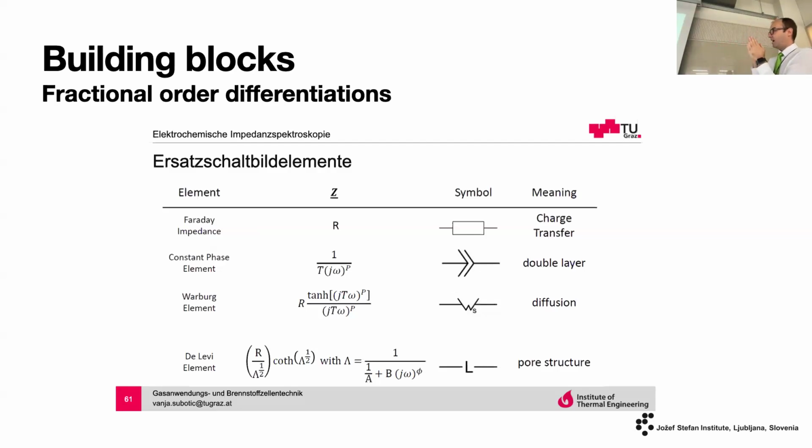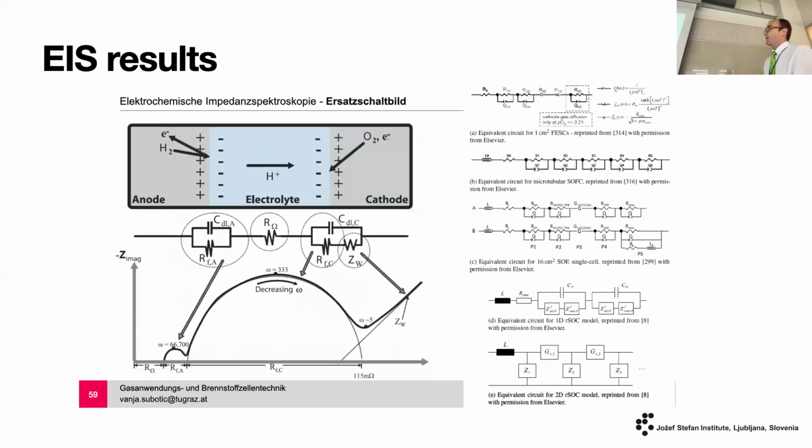So what is our ultimate goal in this case? This is a PEM fuel cell, obviously, but it doesn't matter. On the upper left part of the slide, we have a system that we would like to characterize. So we calculate the EIS curve and get the Nyquist curve below here. And then what we usually do is put in some sort of equivalent circuit model.